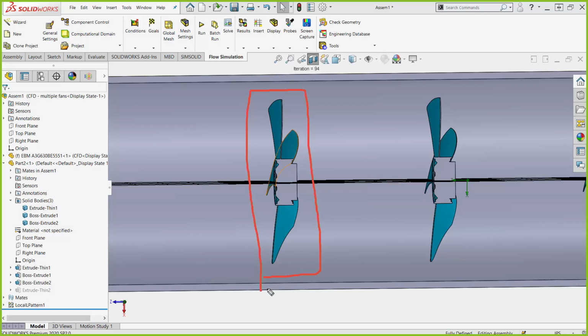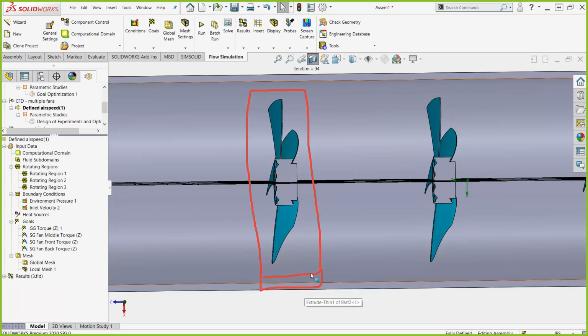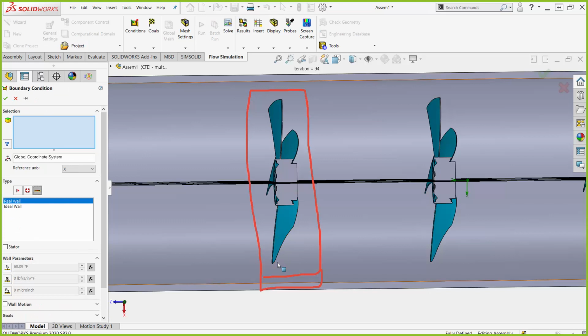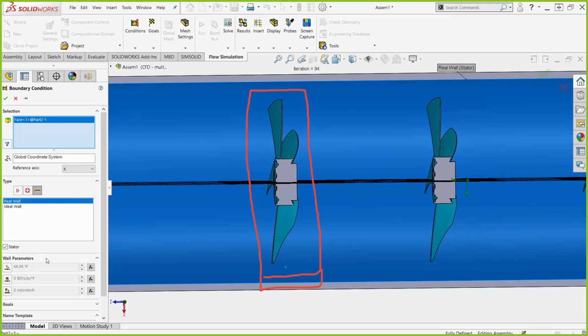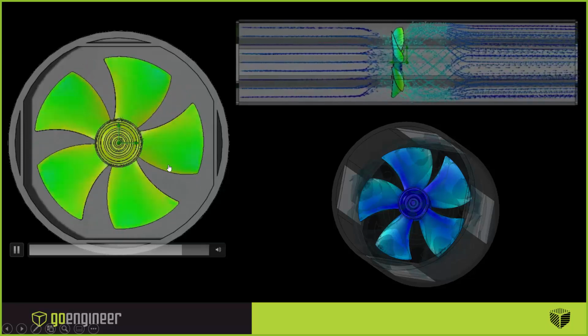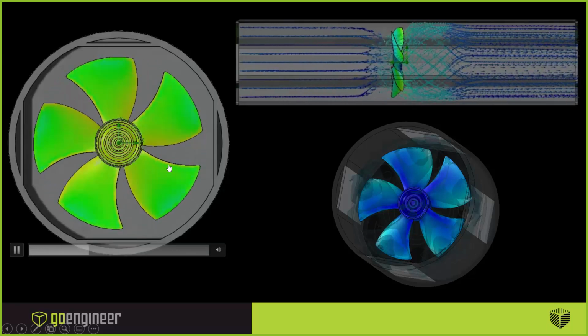Technically, you can get away with it crossing the boundary. There are some tricks, okay? So let's say across the stator, I can apply a wall boundary condition to my face and say it's a stator. So the fluid flow touching that face should still be 0, or velocity of the face should still be 0, and then have a boundary layer, etc. Where it breaks down is when you're using the sliding mesh technique, where it's forcing the part to rotate.